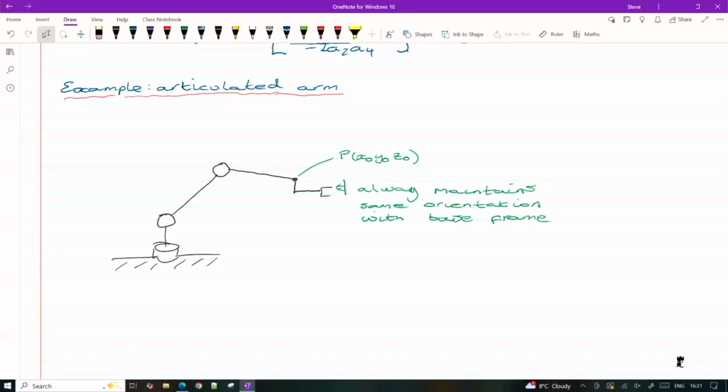Okay. The robot configuration is not exactly like I've drawn here. The second revolute joint is actually attached to the base, and it actuates a link rod that goes up to the elbow to rotate the elbow. But you can think of it as the joint being at the elbow in terms of the analysis. The reason for that is it places all the weight at the base of the robot, so it's quite stable. If you put a large stepper motor at the elbow, it wouldn't be as stable, and there's a lot of weight you've got to move. And it just so happens you can move everything to the bottom and use a set of linkages to drive the elbow. And again, if you haven't looked at the Dobot yet, this will all make sense when you do.